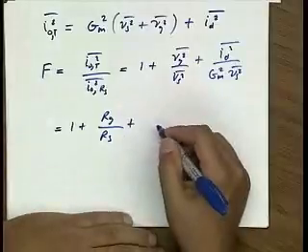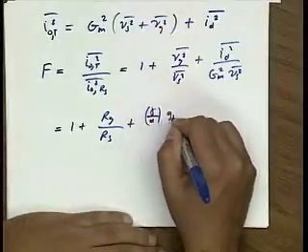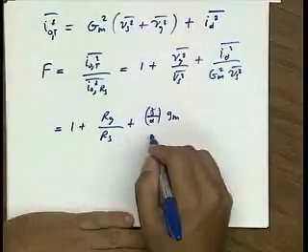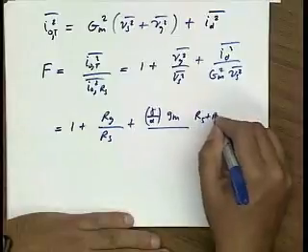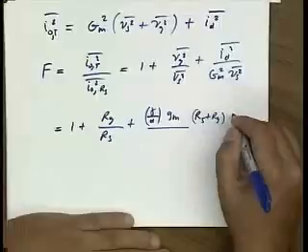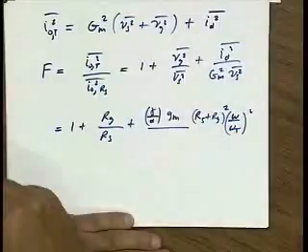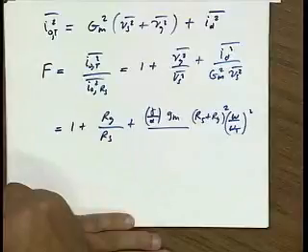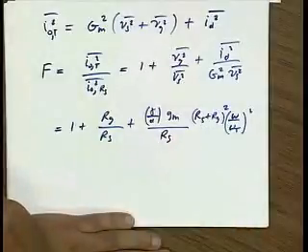For the drain noise current, I substitute gamma over alpha Gm. For Gm squared, I substitute basically 1 over Rs plus Rg, omega over omega t squared. I'm interested in the magnitude, so that goes away. And on the denominator, I have Rs. Okay. Any questions?